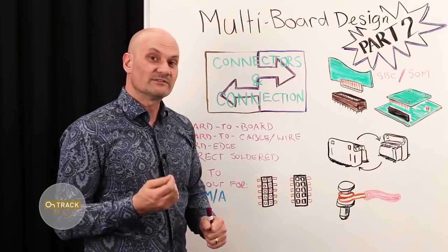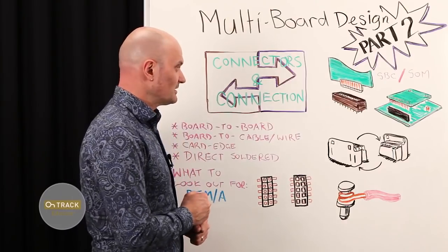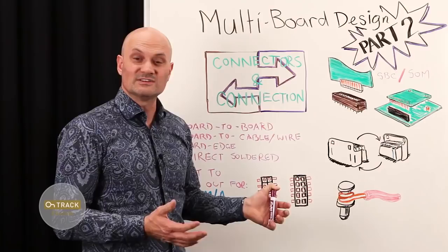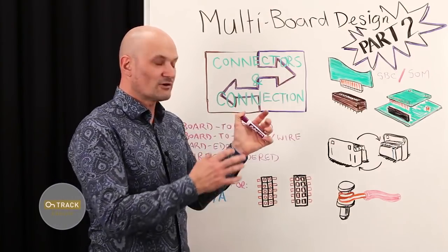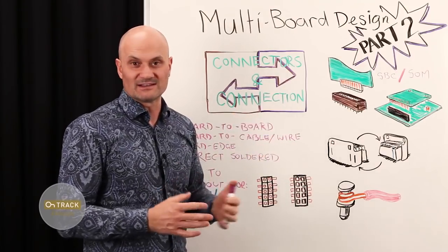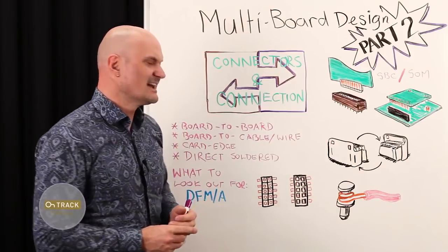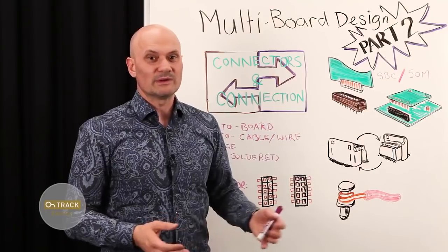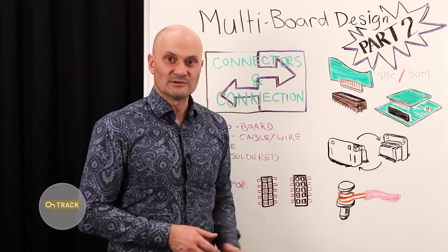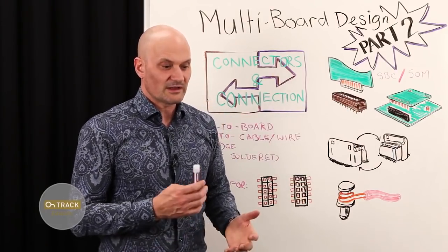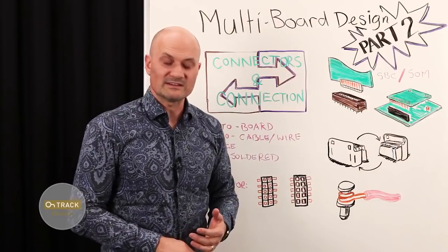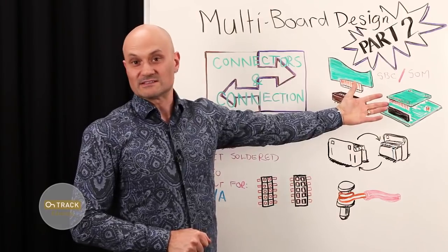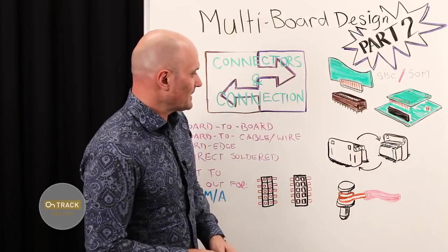They're not necessarily designed for very high speed, for example, and you can put some reasonably high speed through them, but you need to take up additional pins for ground return paths for signal integrity purposes if you're going to do that. And there is a practical limit given frequency, performance and impedance to these as a solution. So you need to decide, are you dealing with very high signal edge rates, or can you get away with a lower cost connector that's not necessarily made for high speed?